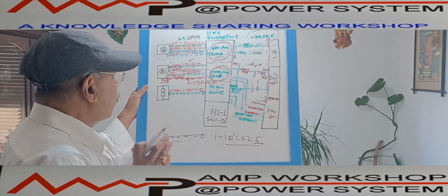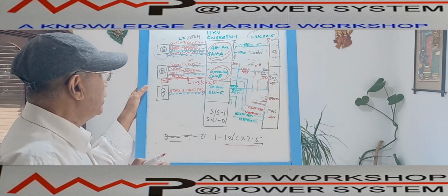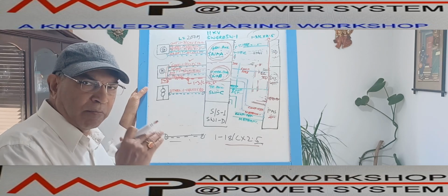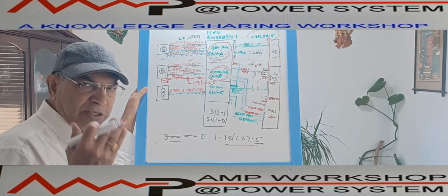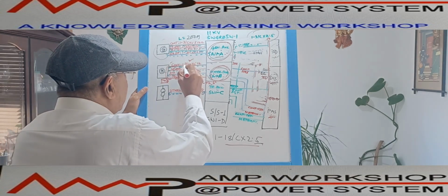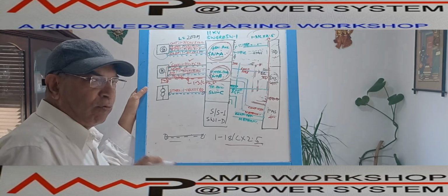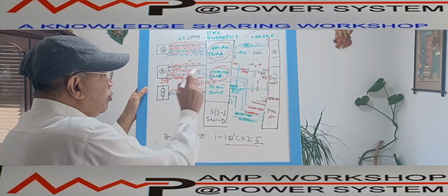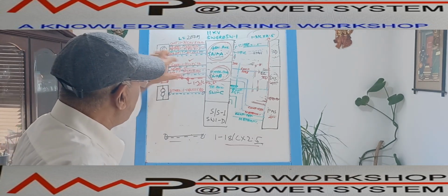And so these are the 4 cables we have considered here. One is a control cable for the circuit breaker on-off from the motor skid. Second is a space heater cable, one 3-core 4 square millimeter cable, and then one 18-core cable for the RTD signal and one emergency push button cable. These are for the motor side.